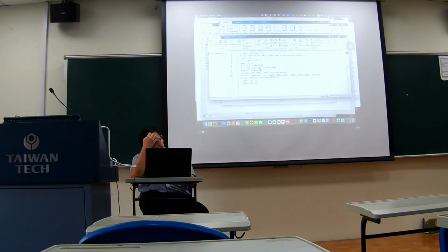Here you can say, basically, you don't really need x iter. You don't need iter. So iteration is inside fmincon. So let's just call this x0. So x star, basically optimal, equals to fmincon. And here I'm gonna call my func, so my function, and then x0.